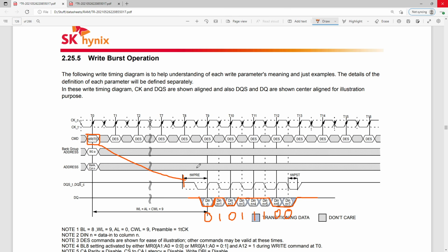It's not particularly common, but you could. If you're talking about a server CPU, that CPU could have hundreds of memory chips hooked up to it. So complex, expensive memory chips would not be good. Having a complex, expensive memory controller is a much better option, because you only need one memory controller for up to hundreds of memory chips.